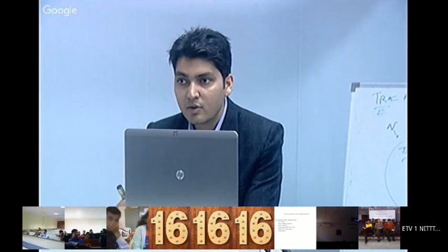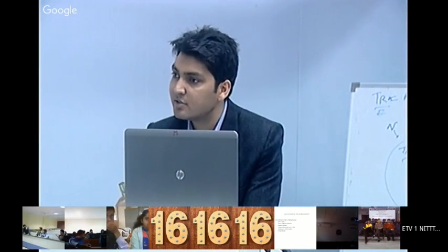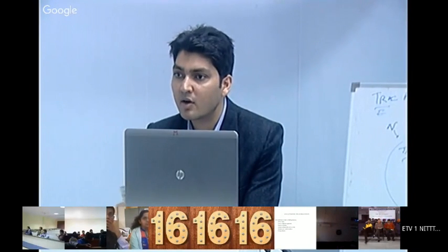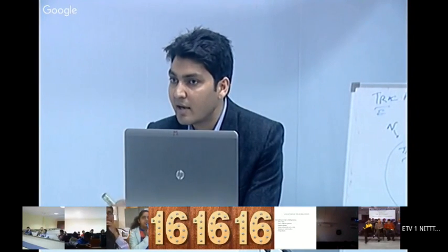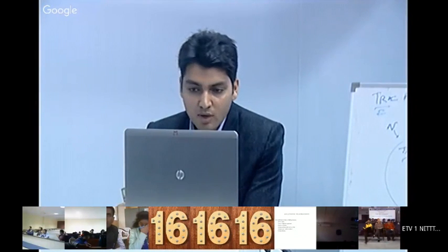At higher altitude, the pressure is reduced and the air density changes due to moisture content and other content. But in Rajasthan, the conditions are very different. There is no moisture and the air density is less. So we also have to consider these parameters to calculate the vehicle torque requirements.